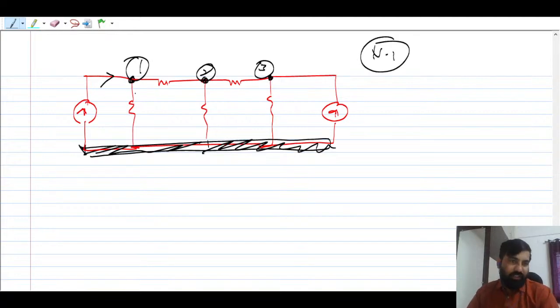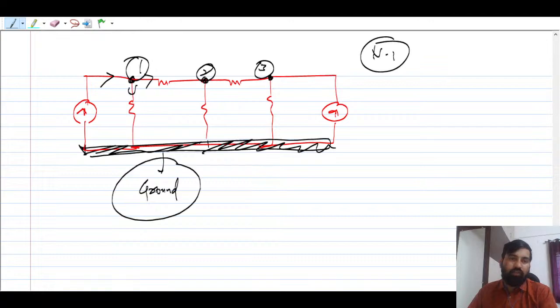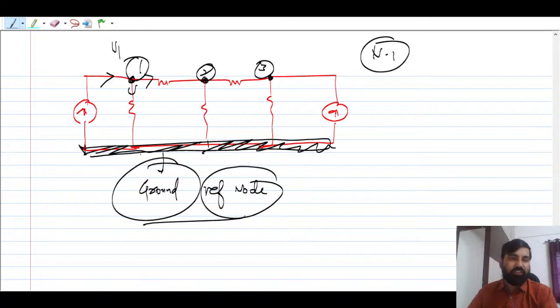Now you should know this current; you can consider the current by yourself, right? And one more important point: all the node voltages you have to consider. You have to write all the node voltages with respect to a ground. The reference node is going to be the ground here, guys. Whenever you are writing V1 here, you should always consider one reference, right? Don't forget that. Many students always forget this. So the voltage across this V1 means the voltage at this point is higher compared to this point, right? So a reference voltage should be there, and then you can write the KCL at that node, right?